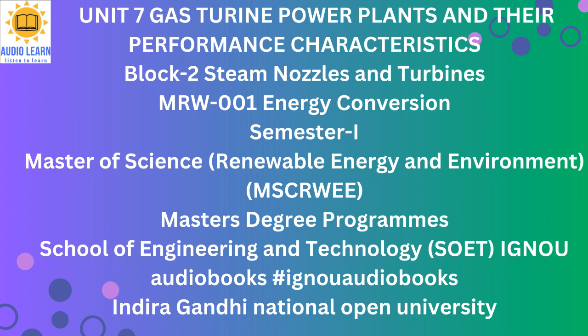7.6 Fuel for gas turbine power plants. Natural gas is the ideal fuel for gas turbines, but this is not available everywhere. Blast furnace and producer gas may also be used for these plants. However, liquid fuels of petroleum origin, such as distillate oils or residual oils, are most commonly used for gas turbine power plants.